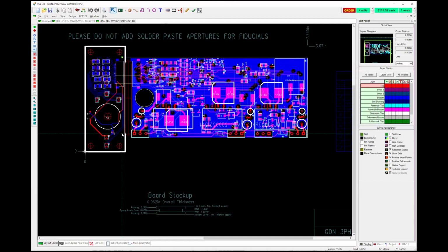So basically, it goes like this: you set up your board outline to fit in whatever enclosure you're going to go with. You select your schematic parts, do your schematic, then you go into here, you place the parts, you place them logically so you can route, and then you'll have the guide wires. And then you want to route your wires. The way I go about it when I route a board, I like to route the power and the ground and make sure everything there is hooked up.